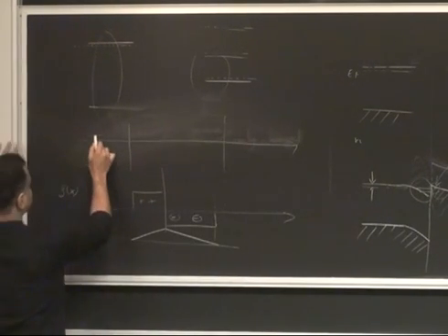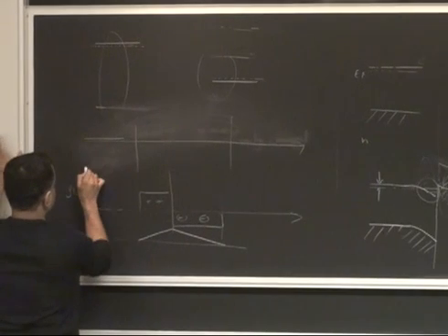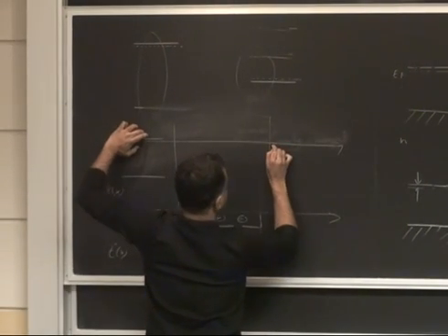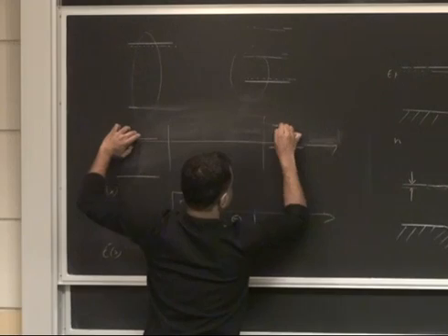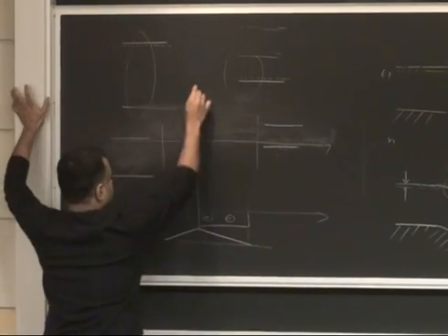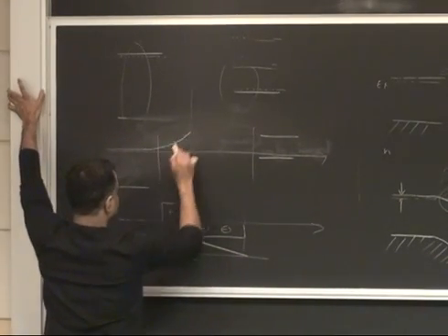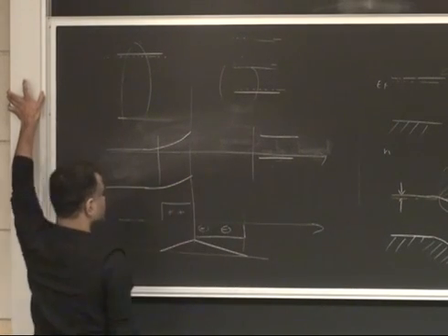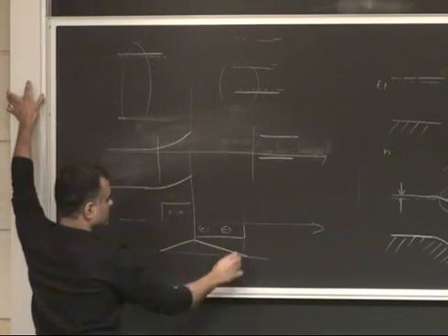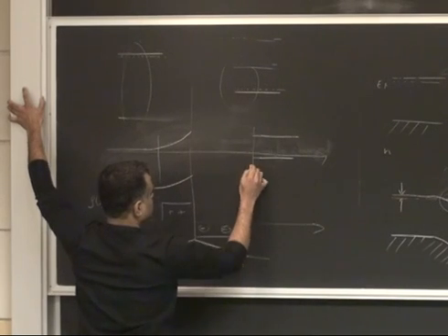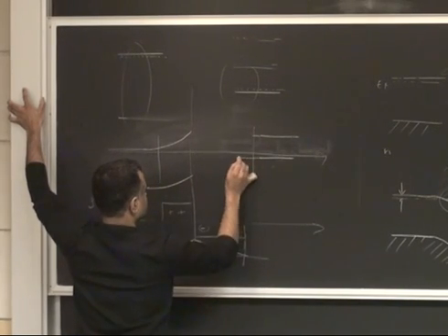Okay. So what we had discussed was, again, far from the junction, nothing has changed. Fermi level minus EC is the same. Far from the junction, nothing has changed. EC is the same. But as I come close to the junction, I see there's a depletion, so the band's going to bend up. Positive charge, the bands are going to bend up. There's depletion in the p side, so the depletion region means the bands are going to bend down.